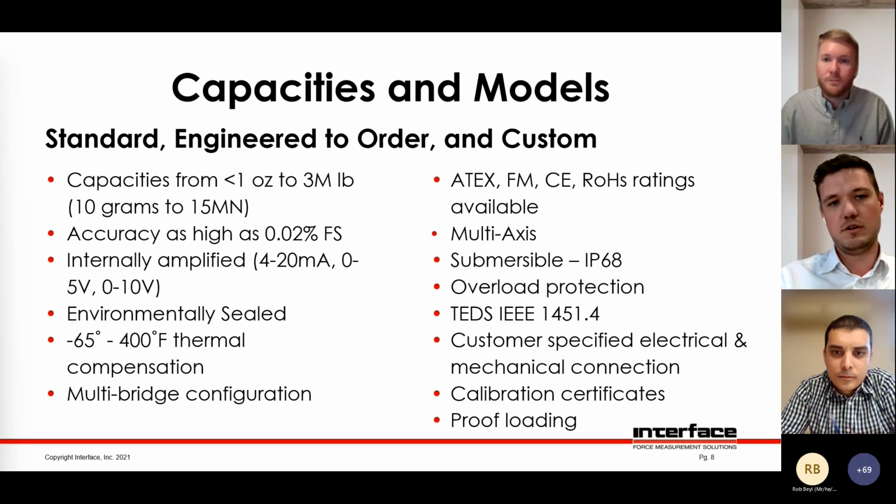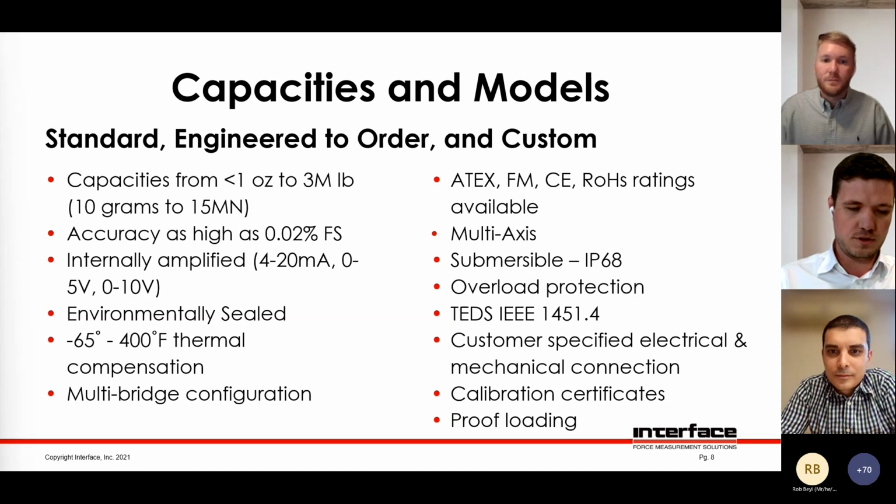Now, most Interface load cells, or load cells in general, are ratiometric output in millivolts per volt of excitation. We can also fit internal amplifiers to the load cells, which will give you control signals. The common ones are 4 to 20, plus minus 10, 0 to 10, etc. Another option would be environmentally sealed. So if you're in a humid or a wet environment, or they're going to be used outdoors, you might seal the load cell to protect the internal components.